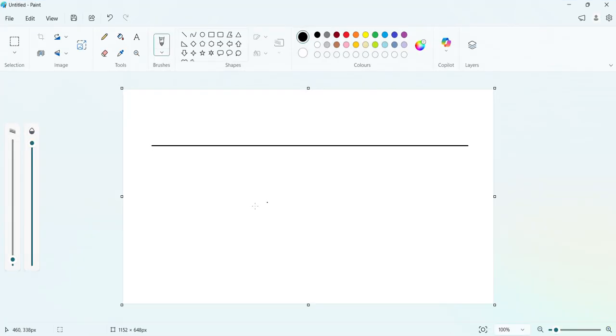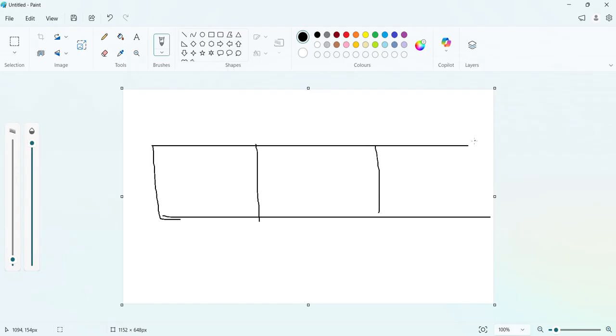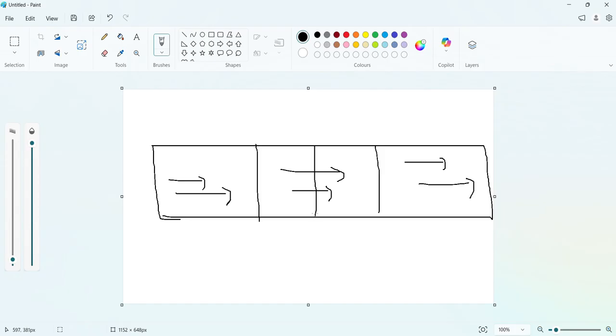So consider this as one road. We have split this into multiple catchments. So water is flowing like this. So characteristic width is nothing but how much width the flow is happening. So this width is there now. So we need to mention this width in that area.